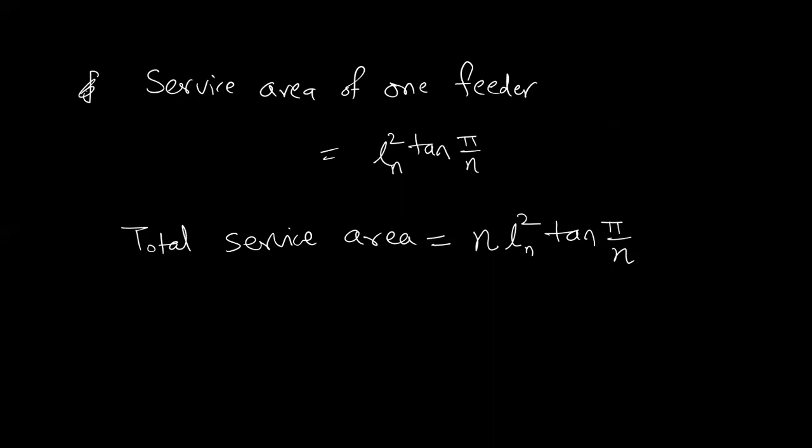Now, what we are interested in is ampacity, or the current carrying capacity. Ampacity is nothing but ampere capacity. So, the capacity of a feeder. That means how much current the individual feeder will carry, like the maximum current going into the individual feeder. According to ampacity, we need to decide the feeder conductor size, its cross-sectional area, and all those things. So how much maximum current can go?